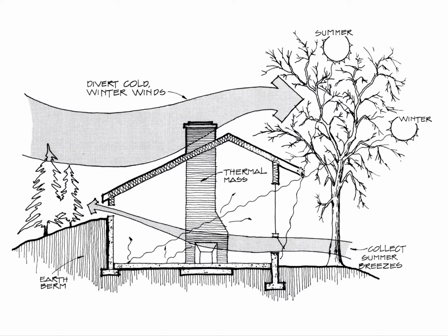Also, I'm going to have these large overhangs. So I'm really going to prevent this sun from having much an effect, or reducing its effect on the heating, the thermal mass inside my home. And then in the winter, it's going to drop its leaves, and I'm now going to get more sun into my space. And then there are all kinds of things you can do with your floor materials so that they will collect and then radiate out the heat at night.